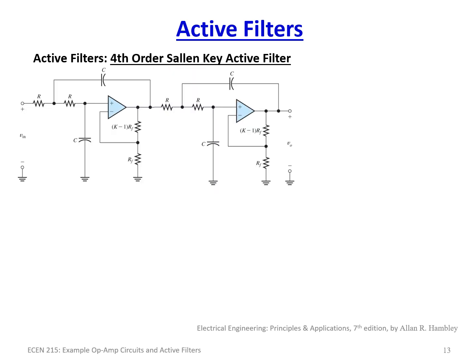So here's another example, a multi-staged Sallen-Key. This is a 2-stage, which means we have an order of 4. Here H naught is K squared. The reason is that, remember, amplifiers cascade, meaning that everything multiplies.